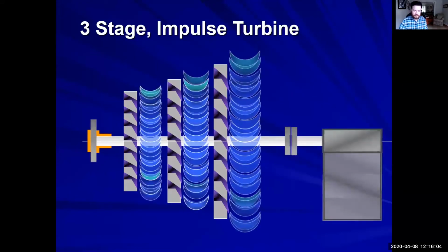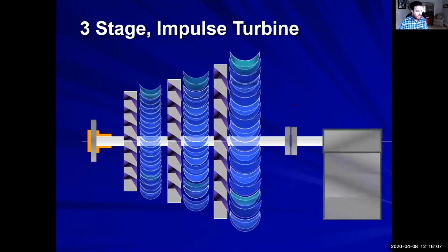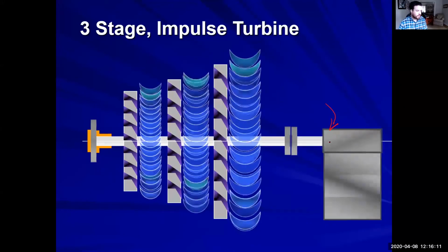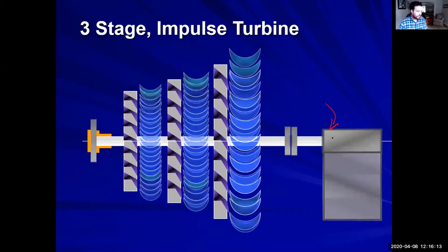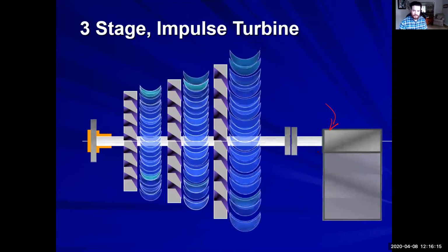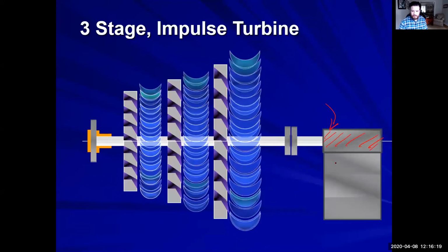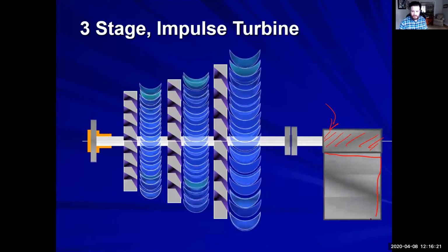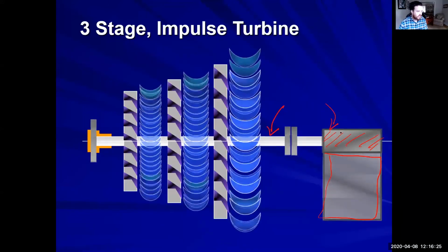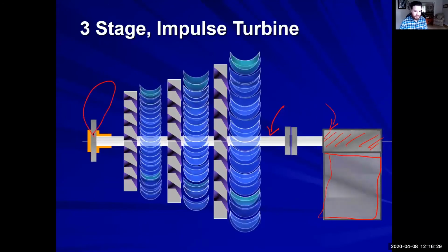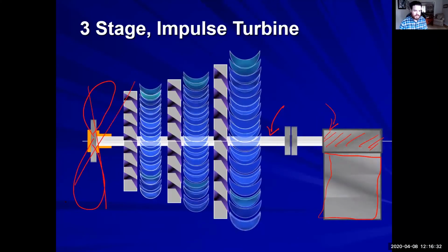Now here's the big thing. The high pressure turbine is geared directly into the main shaft of the ship. This is a smaller pinion gear right here, and then this is a larger gear here. So this shaft right here is not the main shaft that goes through the vessel. This is not attached to the propeller. That is not correct.